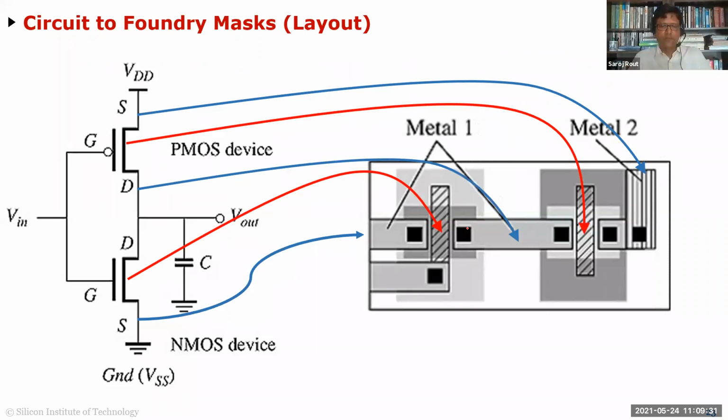So now we go to these devices. You can see each PMOS has this layout. Basically this is your gate, this area over here is your source, drain, and you have this drain connection to VDD from one metal level to another metal level, because there are stacks of metals, and I'll show you maybe in another slide. And same thing, you have an NMOS, which also has a gate area, source, drain. They're all drawn through these sets of polygons, basically.